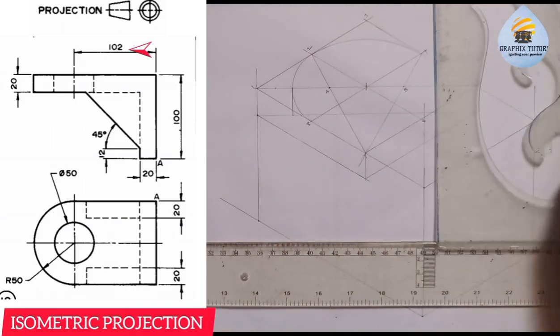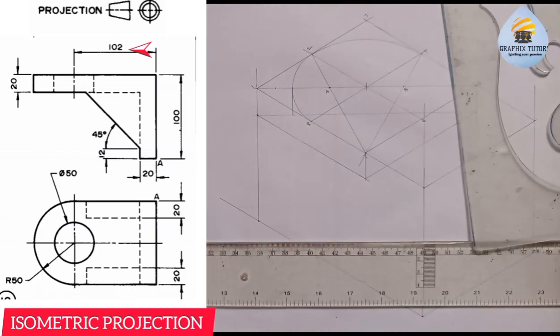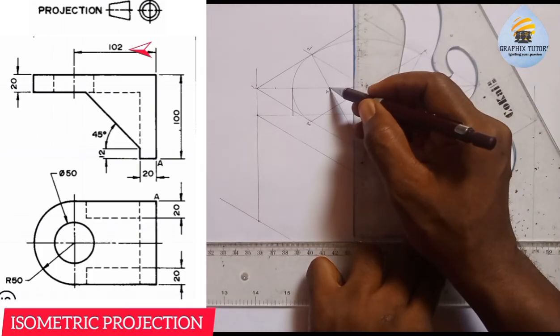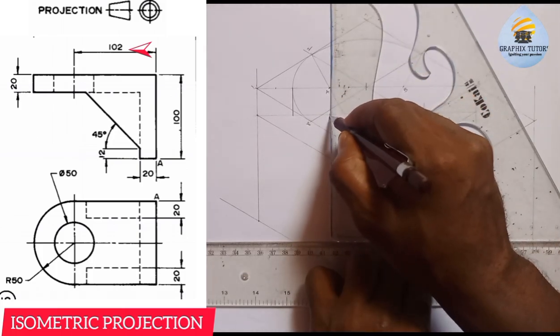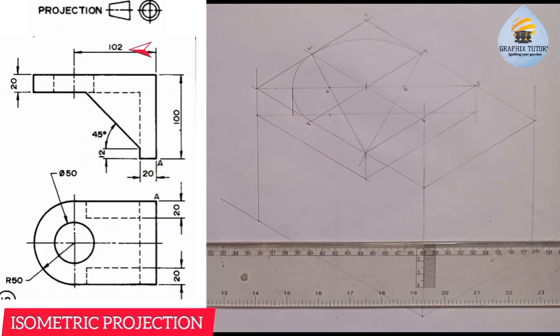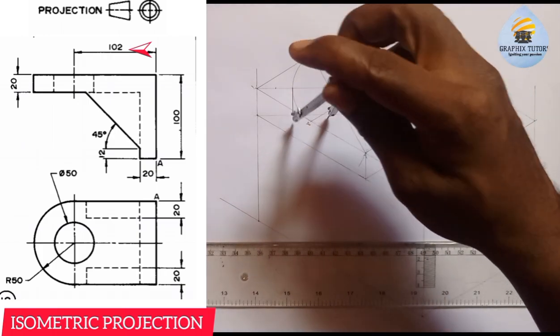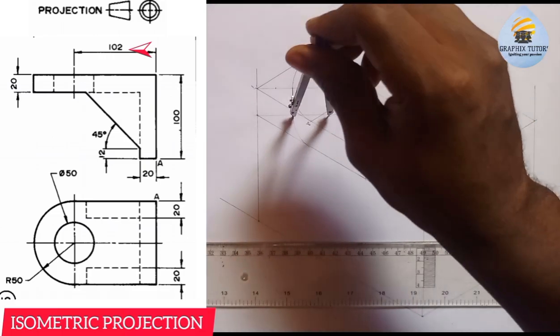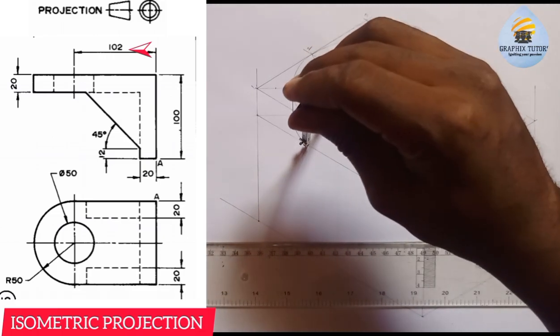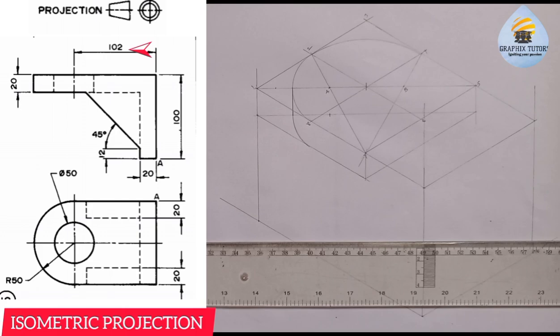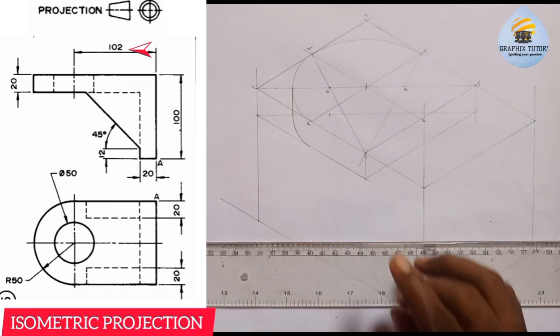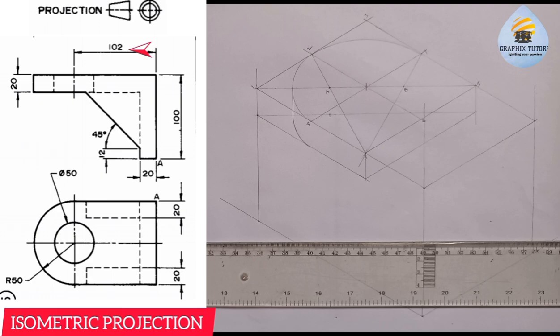And I will transfer point A from this diagonal to the next diagonal using my set square and t-square together. This point A, I'll transfer it down. Can you see that? So place it here and connect here to it will be touching here. Hope you can see that. So if I have done that, the next thing is I would like to bring out that shape out so you see what I'm talking about.